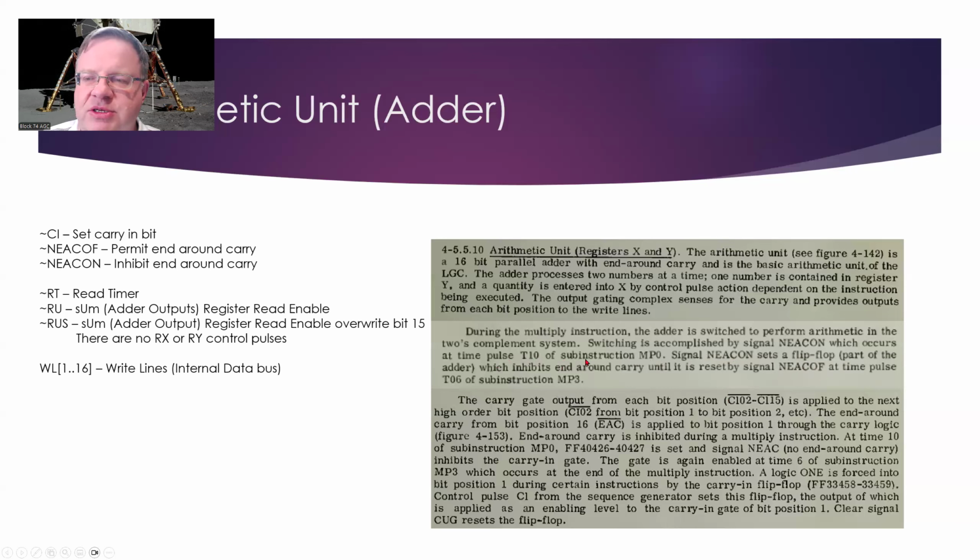We don't need to worry about this too much, at least at this point, because that's tied to the control pulses and the subinstruction sequences. So at T10 in subinstruction MP0, we'll set this NEACON control pulse, which we then use to set the flip-flop, and then we reset it as part of T6 of subinstruction MP3, which is another component of the multiply. We also talk about the carry gate output for each bit position being applied to the next high order. This is where we do carrying, which is how the adder works.